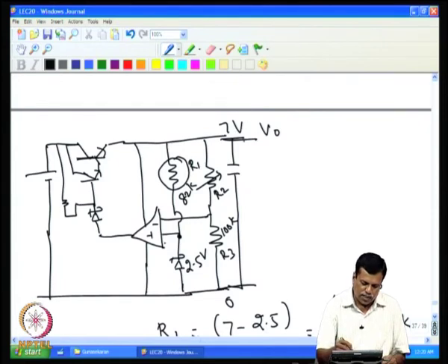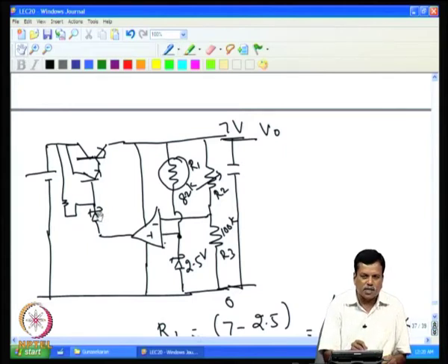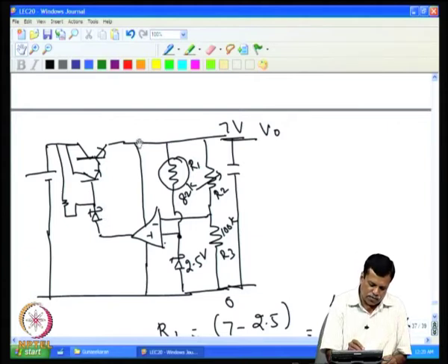By fixing the required R2, one can get the 7 volt that is required at the output. So, you will get a regulated voltage as we explained earlier, and this Zener is used because the circuit has to start initially, since initially the voltage here is 0. If there is 0 voltage, the op amp is not going to work. To make the circuit work, we have biased this using this. We have put, for example, a resistance of say 470k.